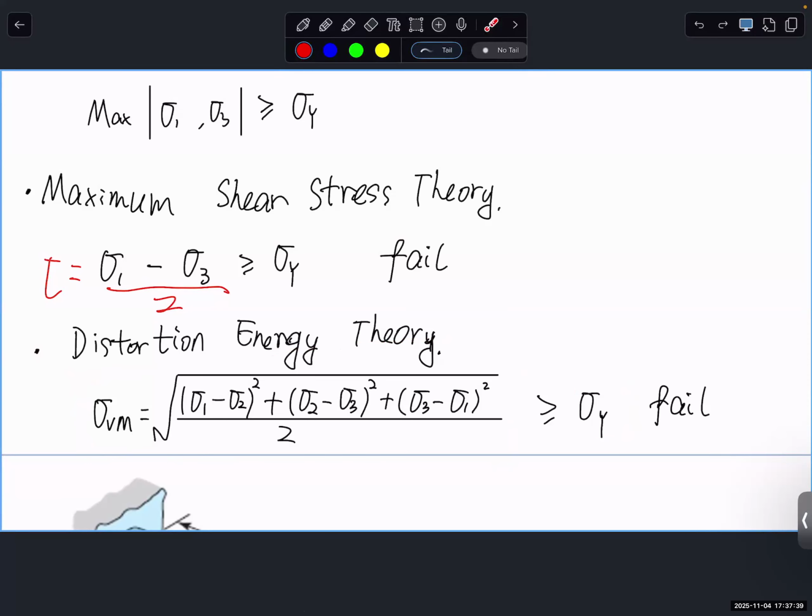It basically means that when you have a complicated structure, let's say you apply force, it can be the force inside or upward or apply a torque, all those forces applied at the same time. And the stress generated at a specific critical point does not necessarily only come from tension or compression, it does not only come from bending or only torsion, it's combined everything. With so many stresses, which one do you want to compare with the allowable stress of the material? There should be one single equivalent value. And the single equivalent value here is the von Mises stress.